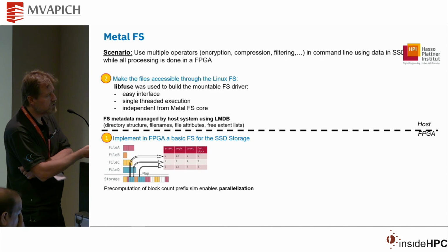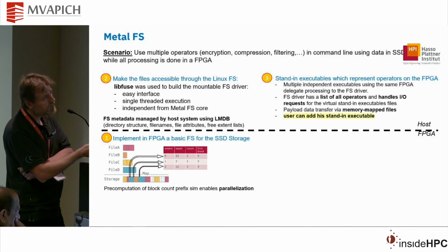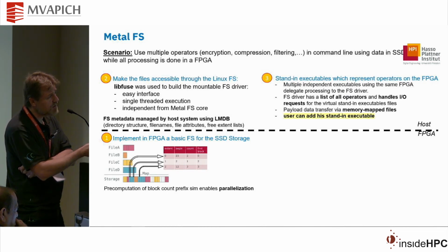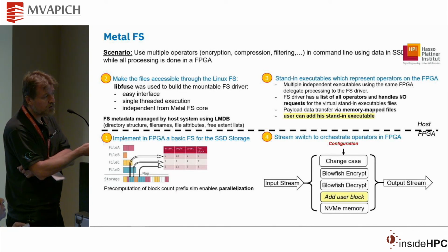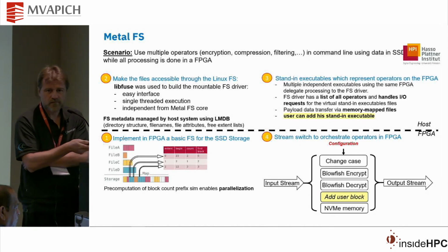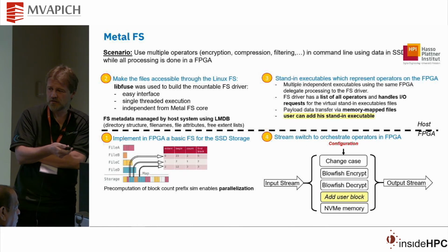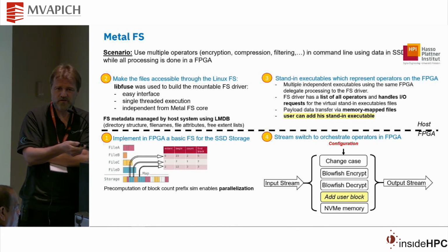So this is the implementation of their system. They make the file usable through libfuse. They have standing executables inside the FPGA. Inside the FPGA, they have defined different operators. They have an input stream. They select the operator: change case, encryption, decryption, and so on. They offer the possibility for you to put your own operator, and this is the output stream. The output stream can be stored in the local memory of the FPGA kernel.